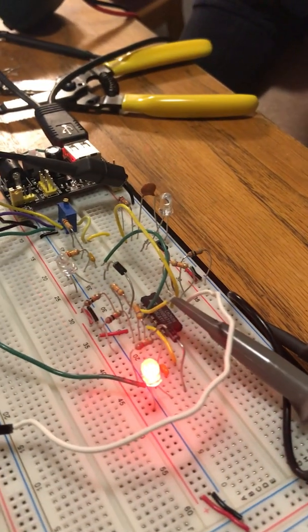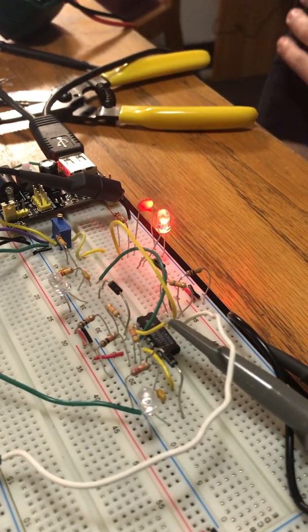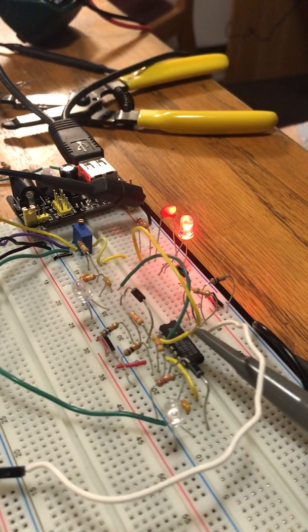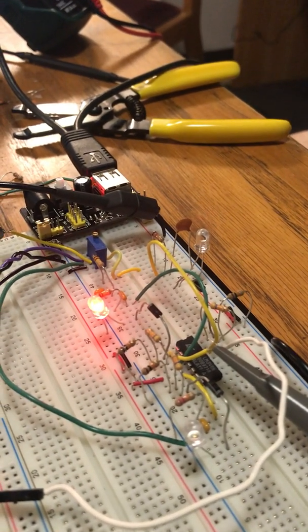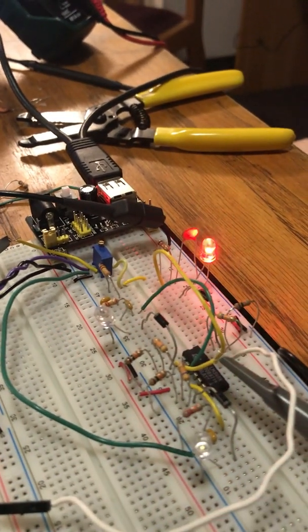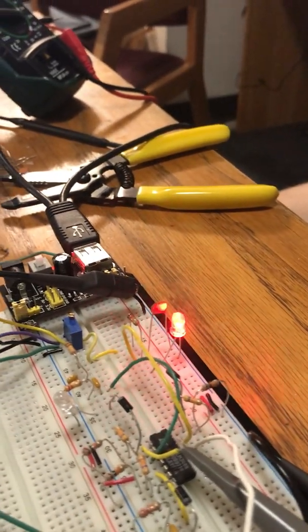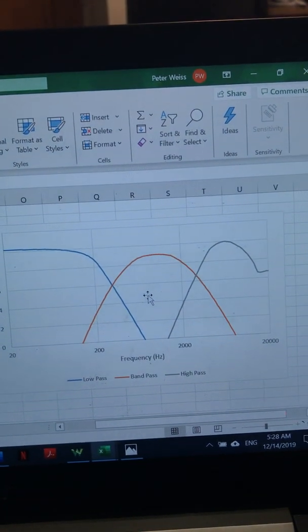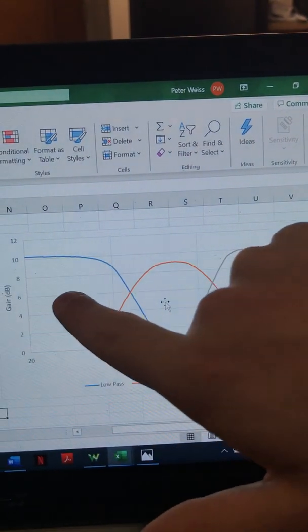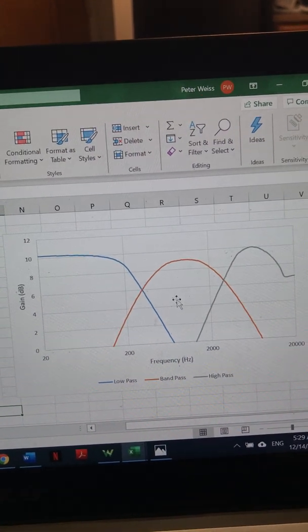So the gain that would have to pass through from a 1 volt amplitude input would have to be around, what did we say, 1.9, which is about 5.5 decibels. I think we said 5.7. Yeah, about 5.7, but these all go above 5.7, about 10. So we actually see that right around where 5.7 is, that's where our transition point is that we calculated.